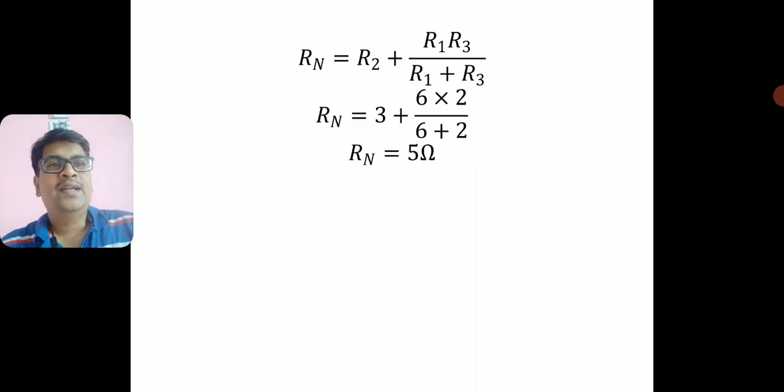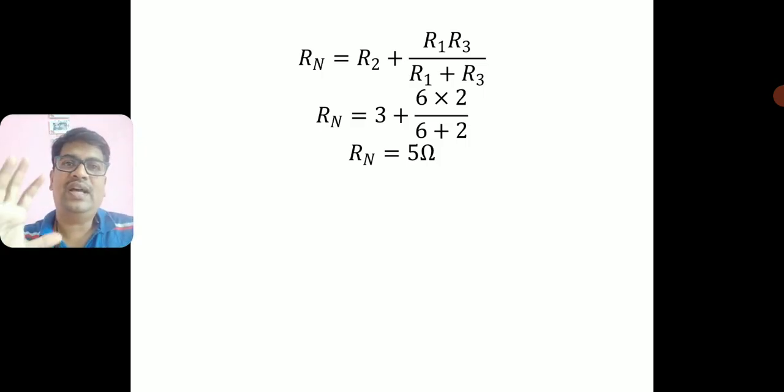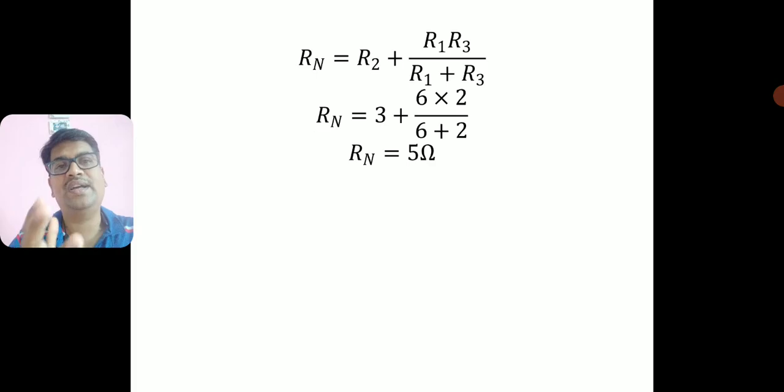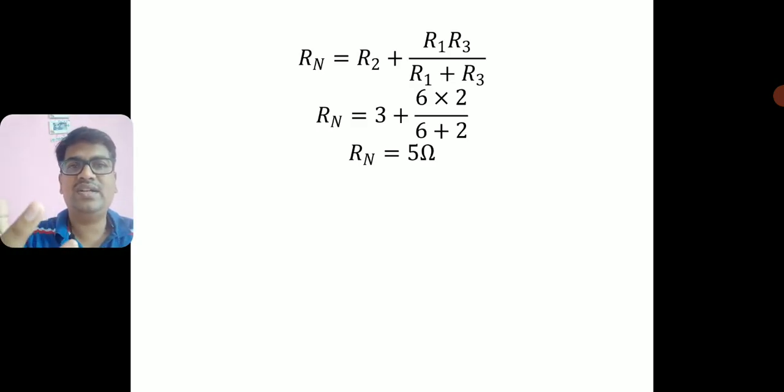Alright, I have calculated the Norton's current IN and Norton's resistance RN. With the help of this IN and RN, I can construct a Norton circuit. You need not write a Norton circuit. It is enough if you find IN and RN; it is understood that we can construct a Norton circuit with them.